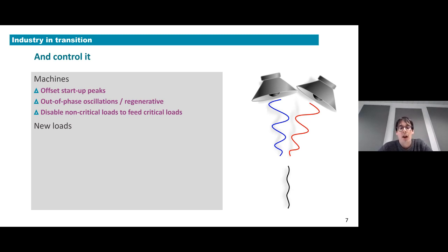Typically there is a lot of inertia rotating inside a machine. If that machine is directly connected to a DC grid, you could stop one machine, one motor with a lot of inertia. You could take the energy out of that inertia and use it to power a more critical element in your grid, which perhaps needs a bit more time to safely stop in case of an emergency.